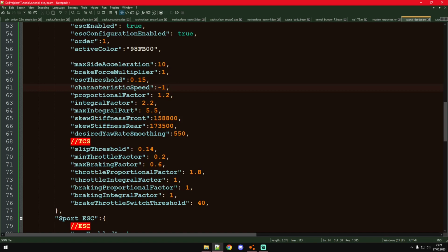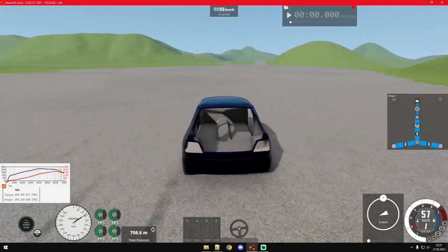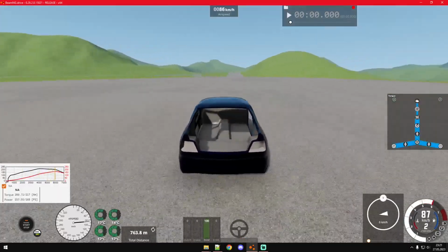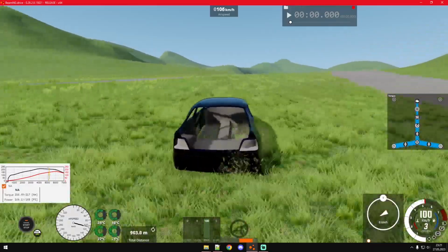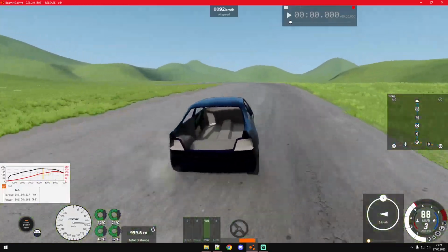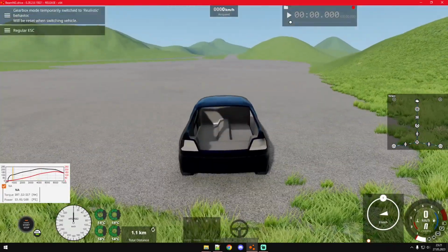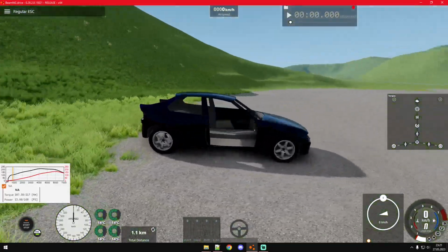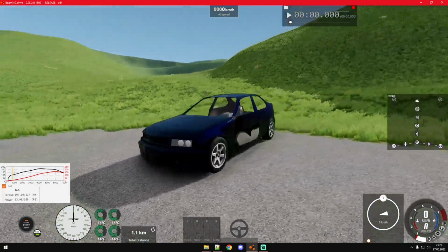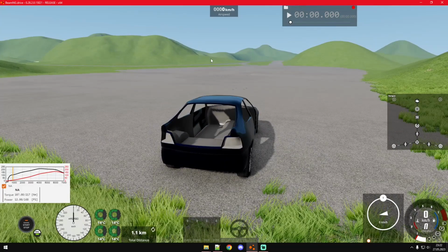It's the speed at which you need twice the steering input to maintain a turn on an understeer car, where you need to put in twice the steering angle of what you would need if the car had a neutral setup, so it was perfectly following the tires.